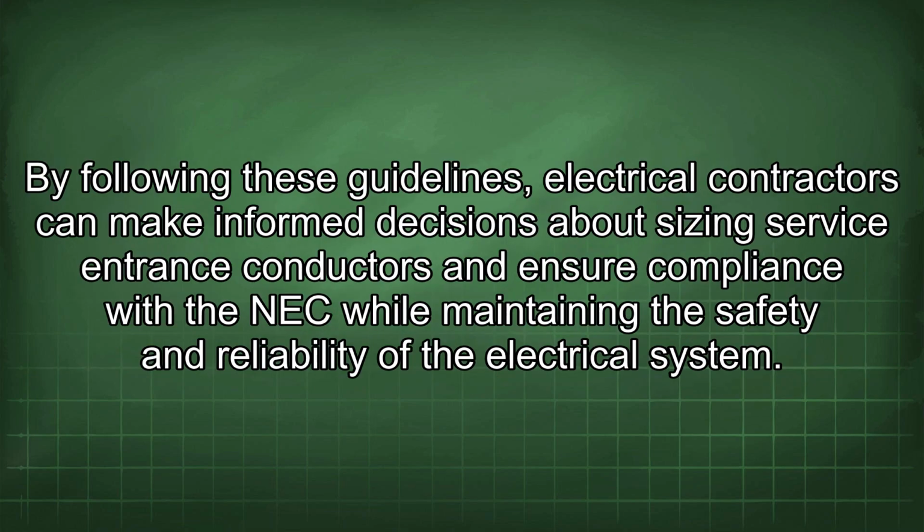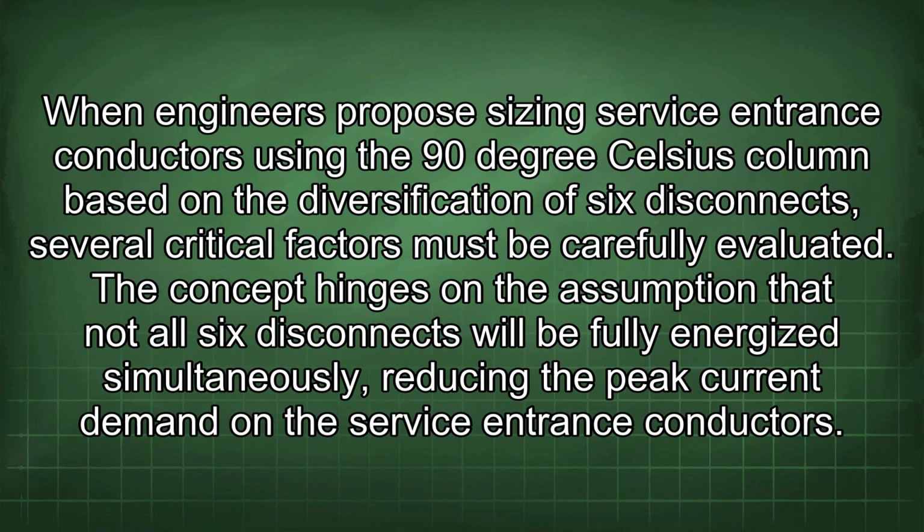By following these guidelines, electrical contractors can make informed decisions about sizing service entrance conductors and ensure compliance with the NEC while maintaining the safety and reliability of the electrical system. When engineers propose sizing service entrance conductors using the 90 degrees Celsius column based on the diversification of 6 disconnects, several critical factors must be carefully evaluated.